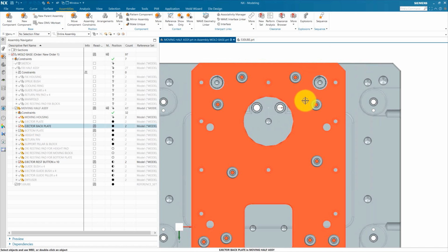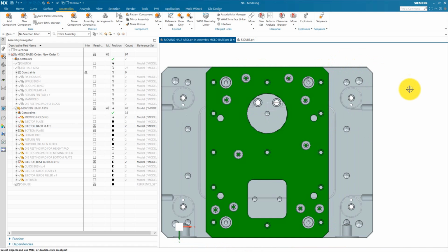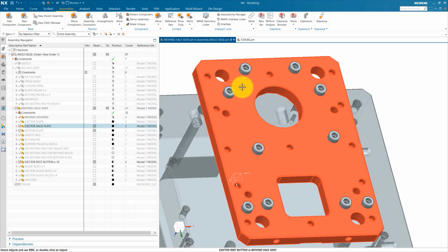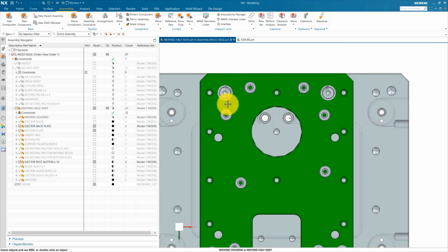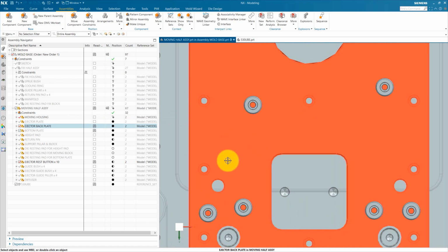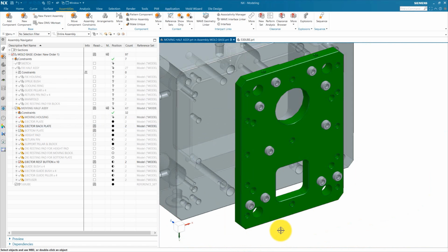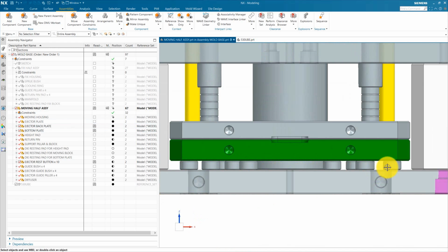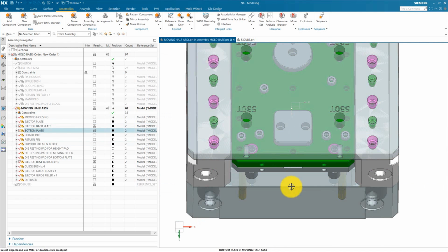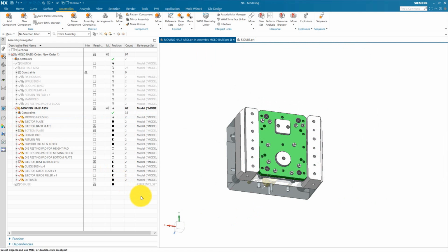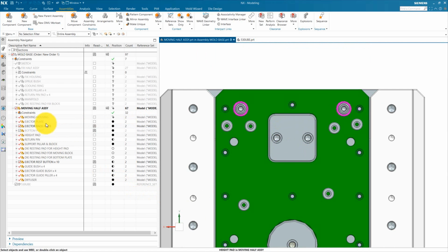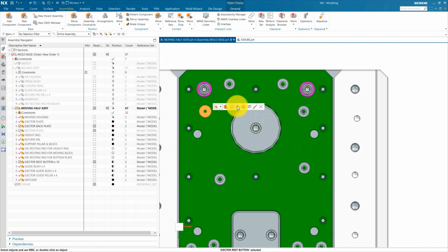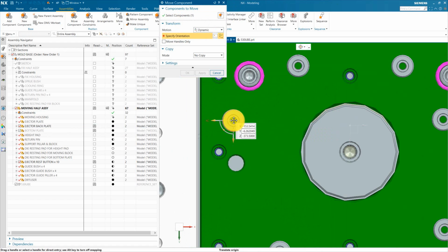This rest button does not need to be constrained. This is only to match with our ejector backplate face and not come into the guide pillar area or the ejector bumper rod hole area. This rest button is going to rest on this bottom plate. You can see here these are our rest buttons, and this is roughly placed, and that is okay. This is only for rest. There is no requirement for this. So we approximately place them symmetrically.